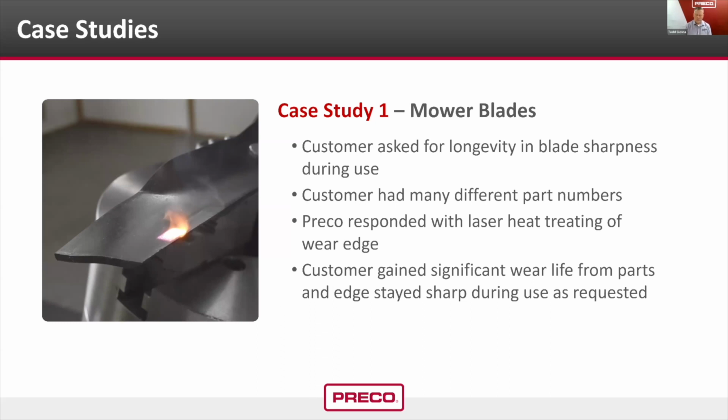The first one on the slide is rotary mower blades used in the agricultural, turf care, lawn care industry, a fairly consumable part. They are 1/4 inch thick. This particular variant was a 1/4 inch thick carbon steel. They were already formed to shape and sharpened, and they were looking for options to harden that sharpened edge, approximately a 1/2 inch wide band going down to the sharpened edge, approximately 1 millimeter deep or 40 thousandths.